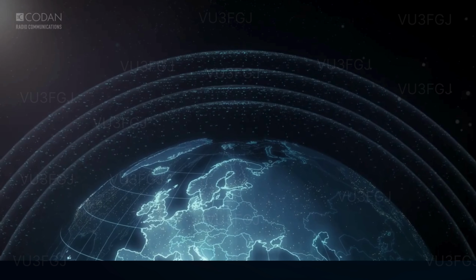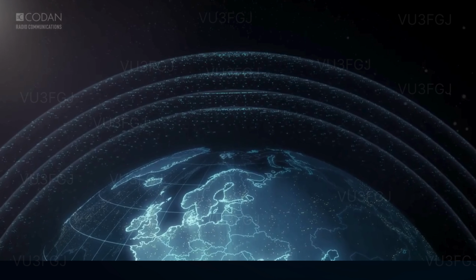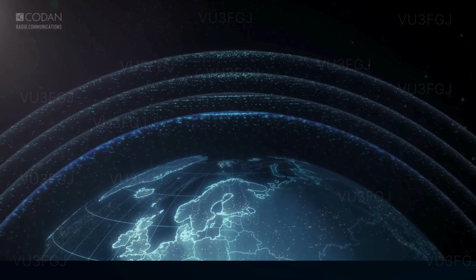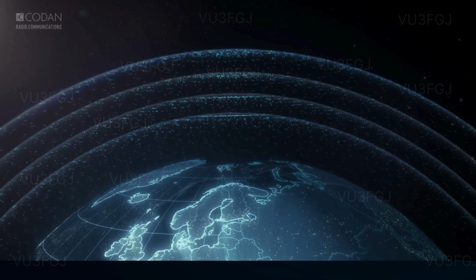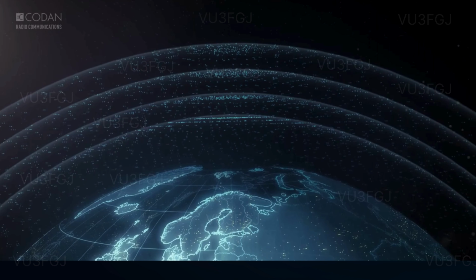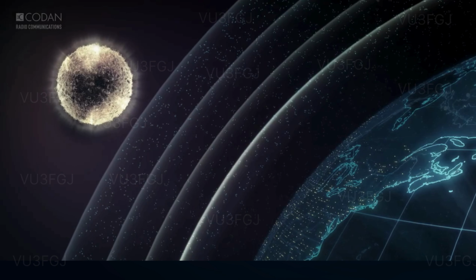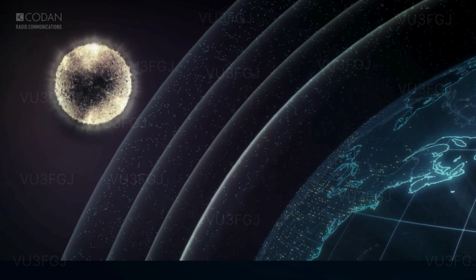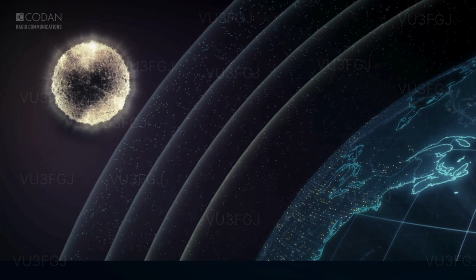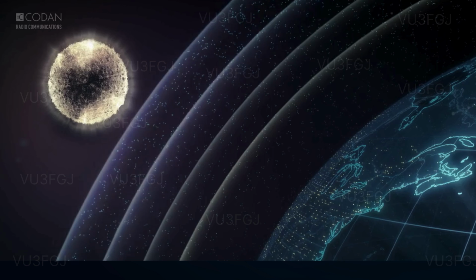The ionosphere itself is made of several different layers that refract the HF radio waves in different ways. These range from the closest layer that exists in the day, called layer D, to the farthest layer called F2. These different layers behave differently in the way that they refract HF radio waves. The D layer in particular can weaken or attenuate the HF radio waves as it contains a higher number of charged particles due to the sunlight. The most common layers used for signal propagation are the F1 and F2. These layers change between day and night.